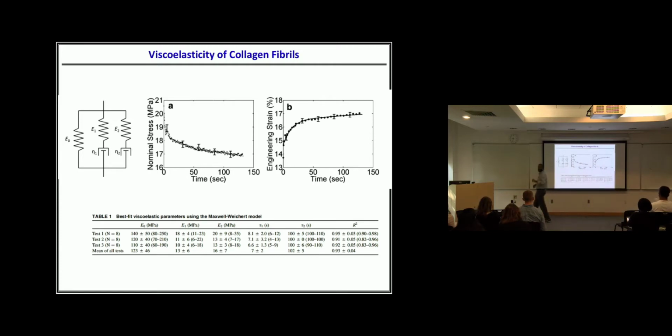There could be many relaxation mechanisms. If you know what a glassy material is, you've heard of glasses, and glasses are very different in their time-dependent response than an elastic solid. A glass is a material that has all relaxation time scales, not just one or two, all. Aging and all that is related to that, the aging of glasses. So you can have many of these processes, but this is the concept: it takes time to break the crosslinks. All right, very good.